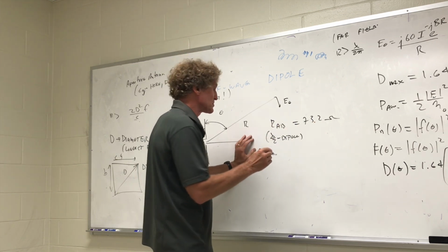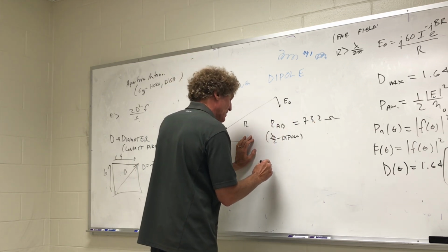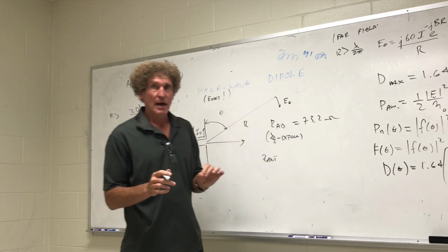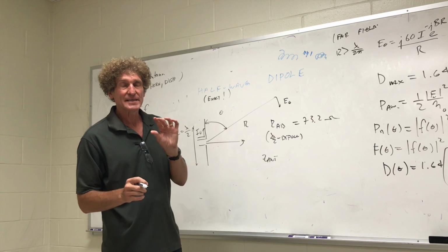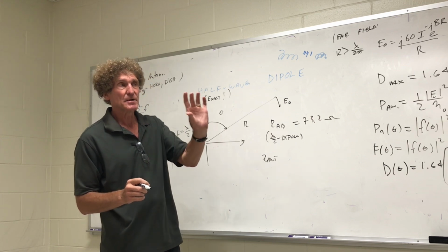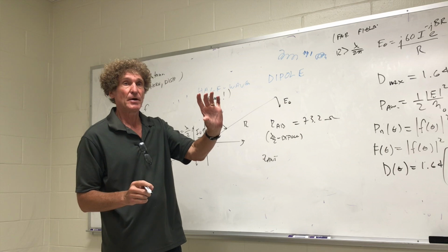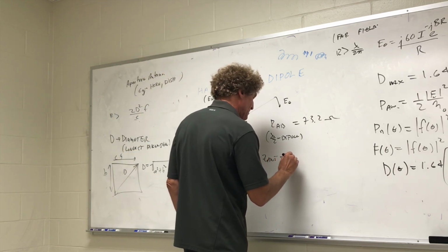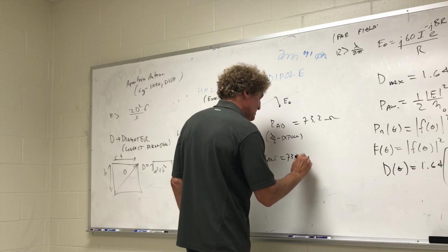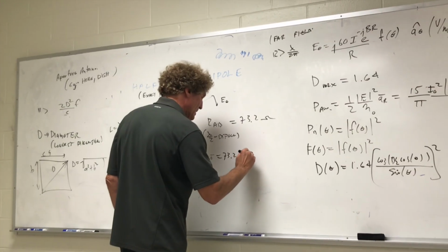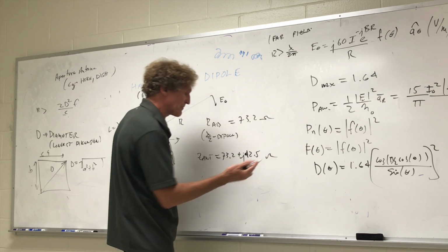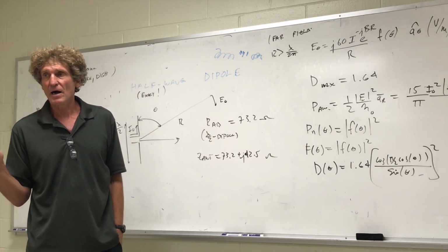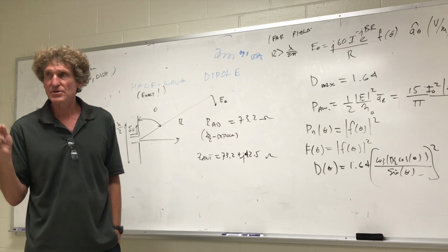Now, this is all for a half-wave dipole here. The actual antenna impedance, so if you were to take a look at what you would replace the antenna with in terms of lumped elements so that you could calculate the current if you had a voltage, the antenna is about 73.2 ohms plus j42.5 ohms. But I want to tell you that 42.5 can change too with the thickness of the wire. Not a whole lot, but enough that you should be aware of it.